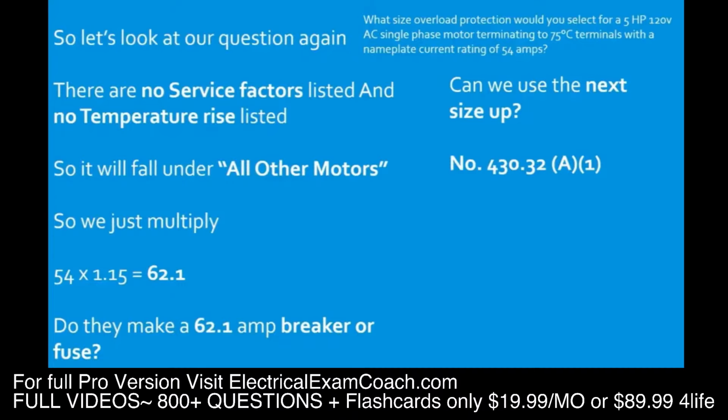So just remember, for short circuit ground fault protection, everything's normal, we can use the next size up. When sizing motor overloads, however, you have to use the next size down. So we still head to our table 240.6(A), and we're going to select the next size down, which in this case is going to be A.